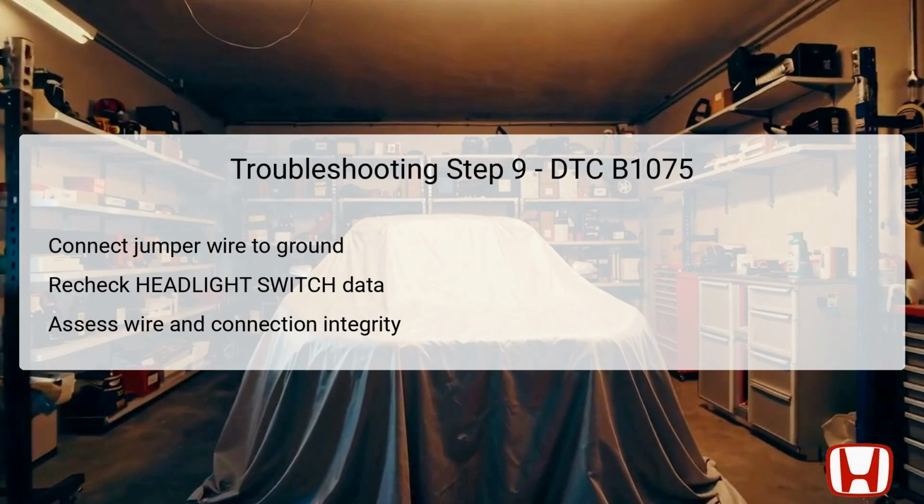If the information indicates on, it signifies that the headlight system acknowledges the connection and the module should therefore be replaced. However, if the status remains off, it suggests replacing the relay control module as a necessary corrective action, indicating that the system cannot complete the circuit.